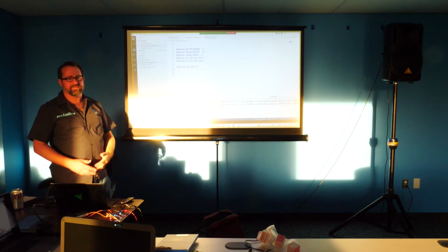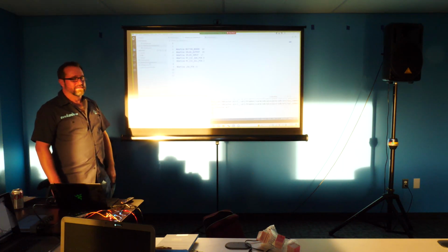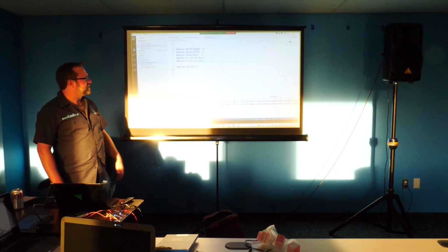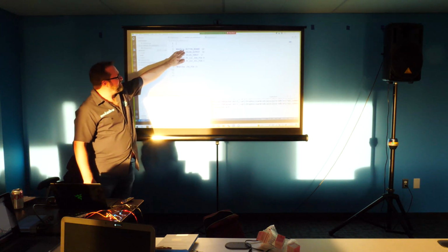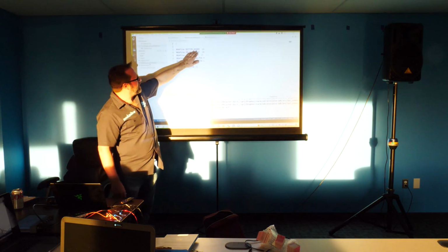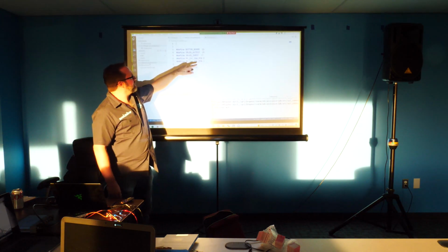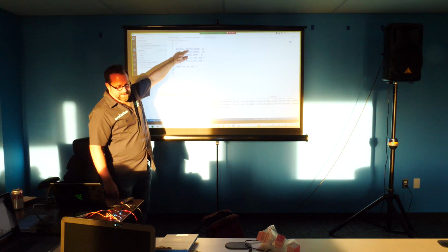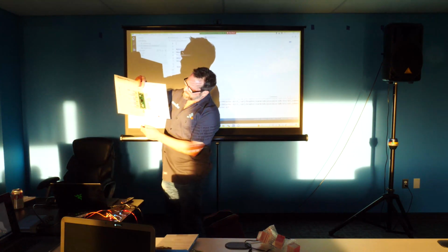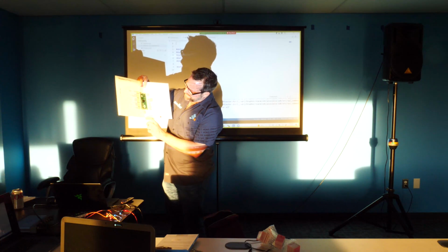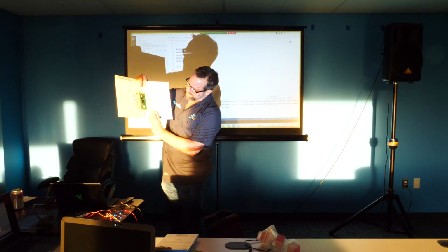It could have code in it, but it wouldn't be compiled. Anyway, this contains defines that say button board is equal to 16. What that is saying for this project is that we're connected to GP 16 right here.